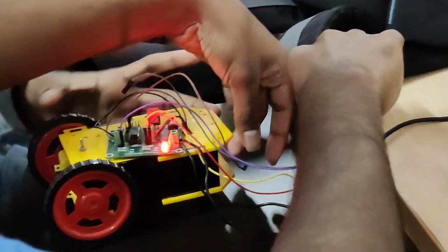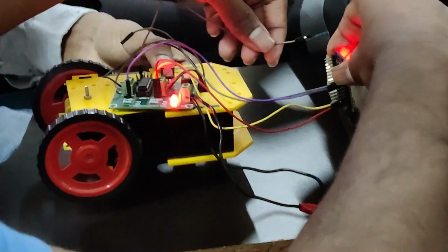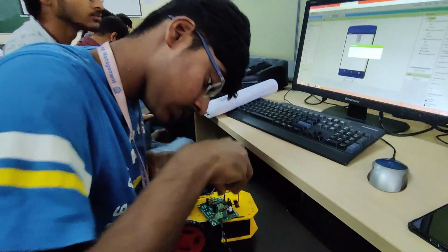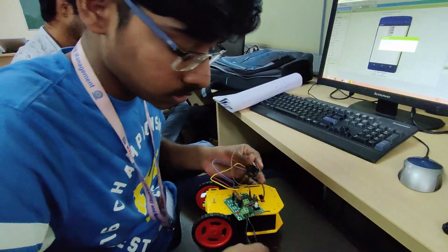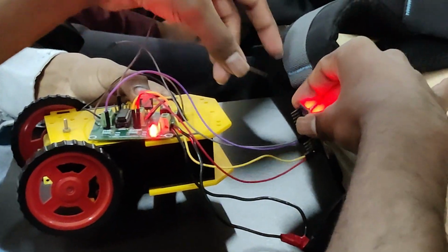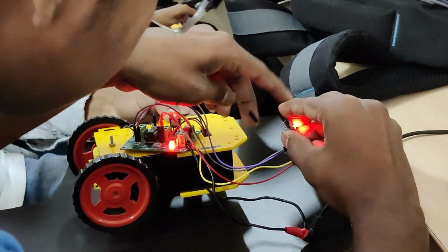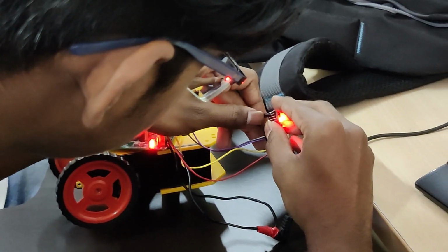So the speed varied from 0.1 to 1, 0.1 the least and 1 for the max speed. But this time we also need to change the pins from digital pins to analog pins. So we did some research on that and we got to know that the analog output pins are the same as digital pins, that are D3, D5, D9, D10, D13. So for the left motor we changed the pins from D3, D4 to D3 and D5 and the right ones remain the same, as these pins are analog output pins as well as digital pins. So that's how we controlled the speed of the car and successfully finished the project on time.